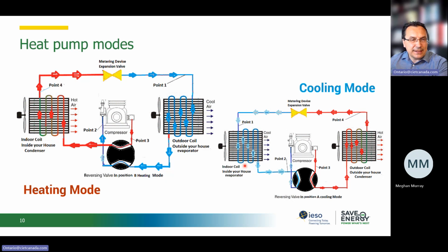So this is where the refrigerant evaporates, absorbs heat from the air, cools the air, and then it goes outside into the heat exchanger that's in the outside air, and it will reject the heat by condensing in that heat exchanger. So if we reverse the function of the 2 heat exchangers, we can use the same air conditioning system for heating the space.